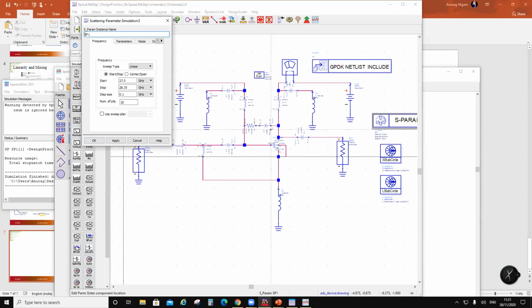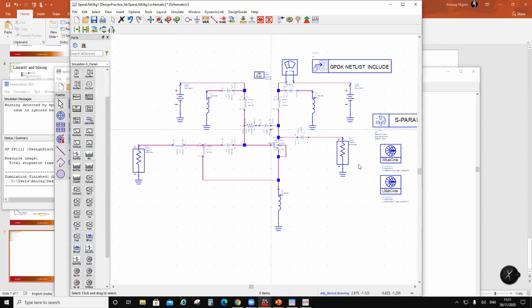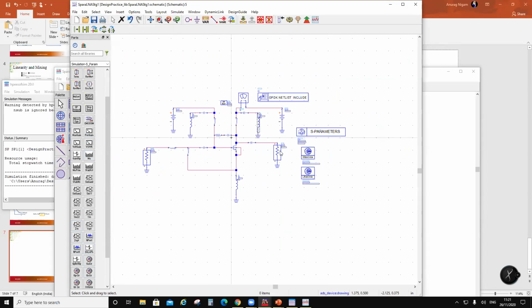If you want to plot noise figure circles, you can plot noise figure circles. But what I have to do is I have to just make this active. And all I have to do is simulate this again. But then there is an option because the IEEE standard defines it at 16.85. So there is an option block here. Where is the option?